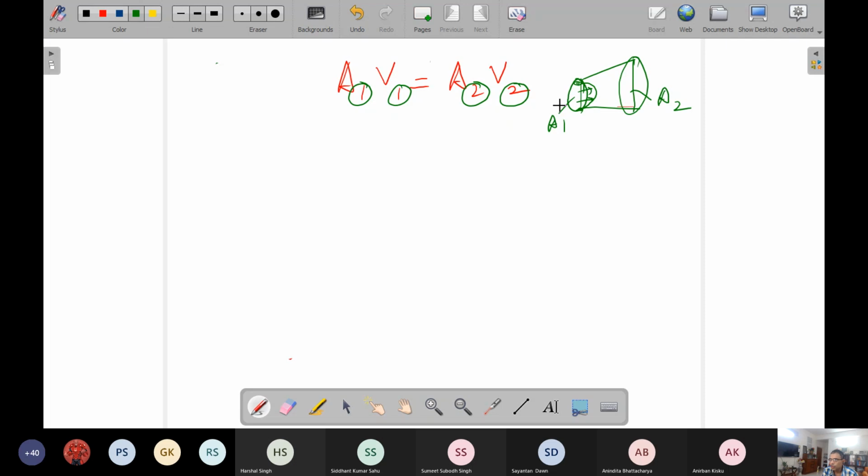Okay. So since you do not have that universal V1, then what is this V1? If you now recall that just now we derived the formula A1 U1 average is equal to A2 U2 average under certain restrictions. Let us say that all those restrictions are satisfied. So under those restrictions, what is the meaning of this U1 and U2?